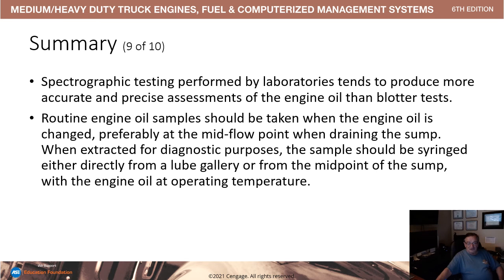Spectrographic testing essentially shines a bright laser-type light through the oil, and it comes out with a band of light that determines what elements are in the oil. Routine engine samples are taken and sent to a lab, and you get an analysis back as to what the conditions of the oil are and what byproducts are in the oil.